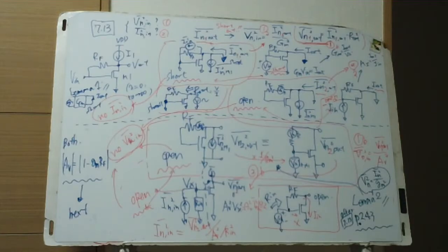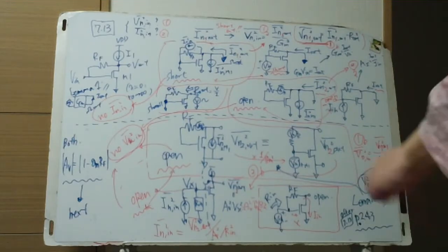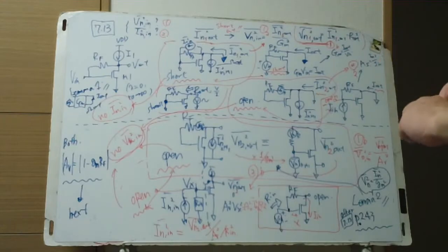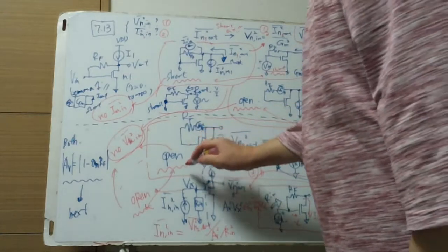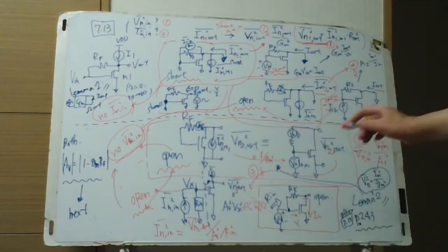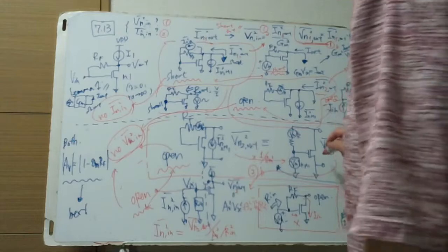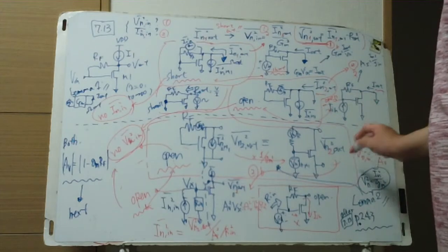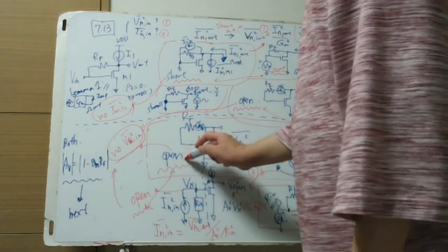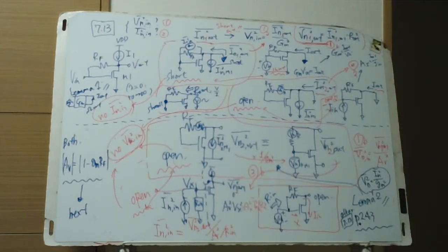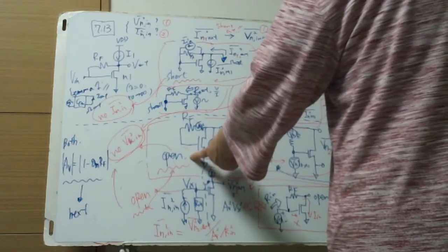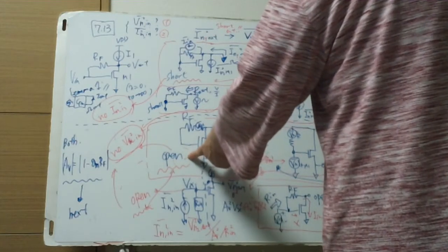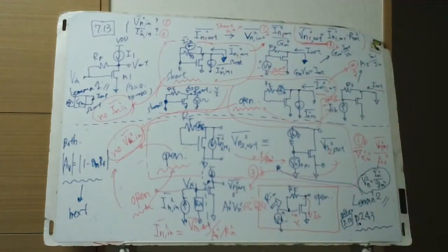Input referred noise. But when open circuit, there's no input referred noise. Just because of that, I think when we utilize the open circuit model, we don't derive the input referred voltage from the output voltage. Total output voltage divided by AV is not the open circuit input voltage noise, because we don't have input voltage noise appearing when the input is open. So we don't use this.